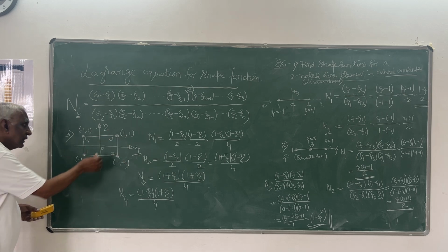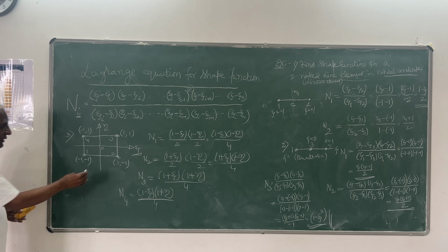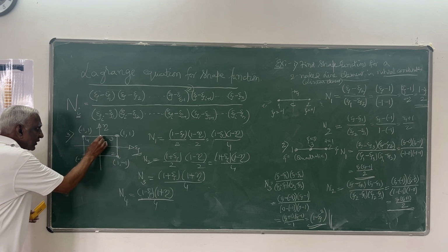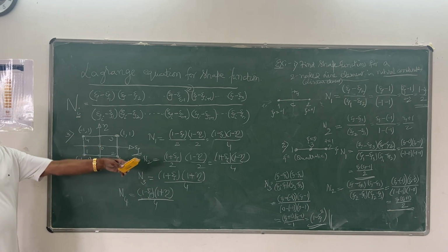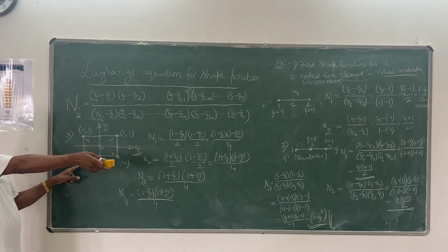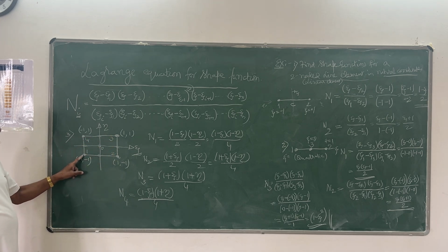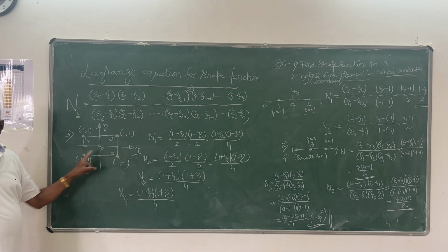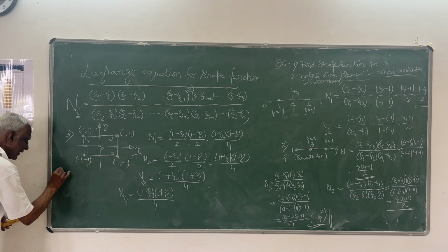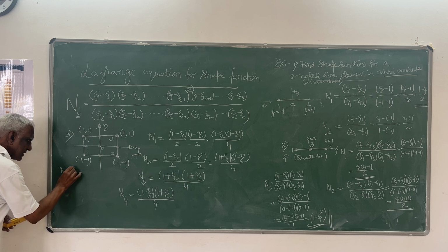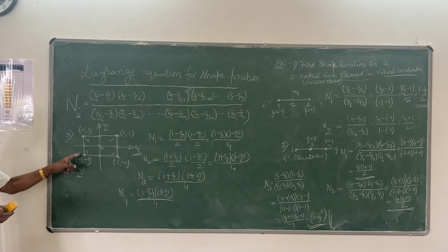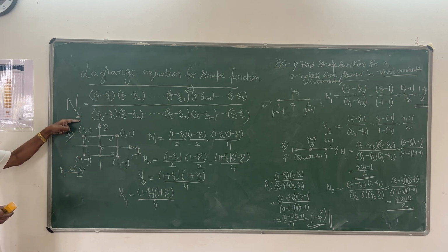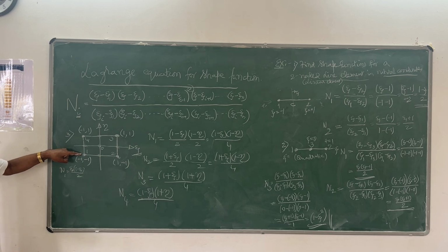Or likewise, 9-noded also you can write. You remember that quadratic element. For 9-noded, if you want to write N1, this is ξ into (1 minus ξ)/2 for this; in the η direction, that's again the lower first node only.